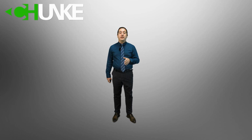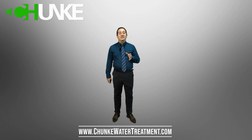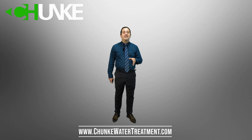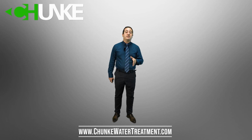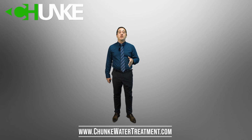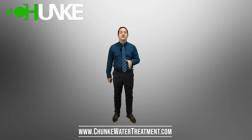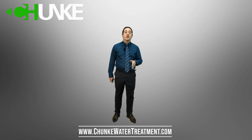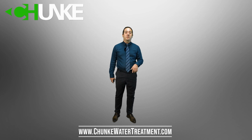I want to tell you again, if you design the system according to these steps, there is a probability that the designed system has some problems. So it is necessary to analyze the system using software such as ROSA or WAVE to fix the errors. Because as a water treatment manufacturer, for all systems we first check with software to see if there is any design problem. It is very important. If you want to learn how to use these software, please write in the comments.